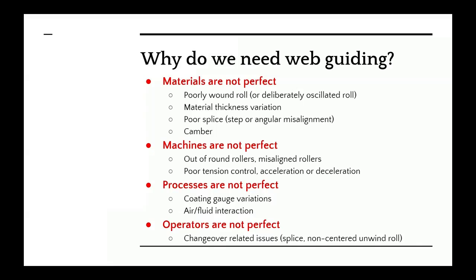You might also have tension control issues. If you don't have enough tension, you don't have traction, then that's going to be an issue. Whenever you have acceleration or deceleration, that might also cause the web to mistrack.